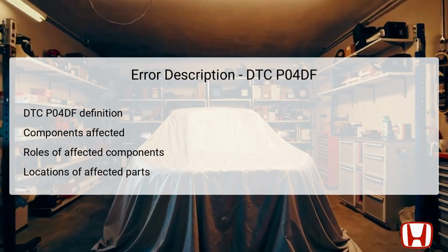maintained during operation. Both components are located within the engine bay, with the EVAP canister purge valve typically mounted close to the intake air path, and the vent shut valve near the fuel tank. Proper functioning of these parts is vital to maintaining low emissions and adhering to environmental regulations.